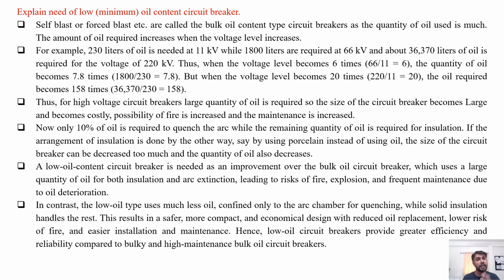Now, only 10% of this oil is required to quench the arc, while the remaining quantity of oil is required for insulation purposes. Now, if the insulation arrangement is done in another way, that is using solid insulation, that is porcelain or bakelite material, or say epoxy resin, instead of using oil.